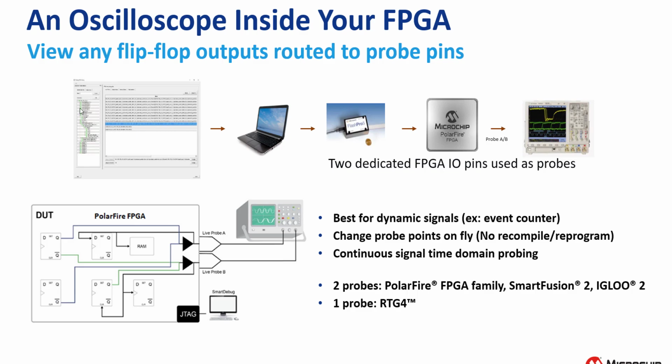You can change the probe signals on the fly without recompiling the design or reprogramming the FPGA. This is a major advantage and can save a significant amount of debug time.